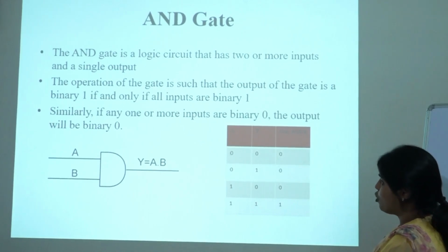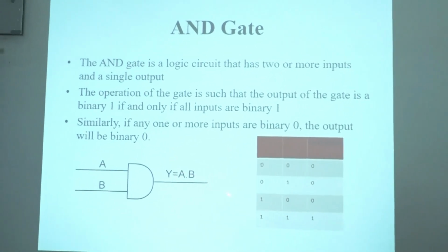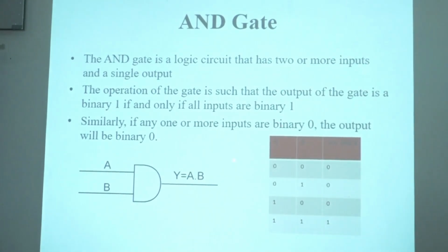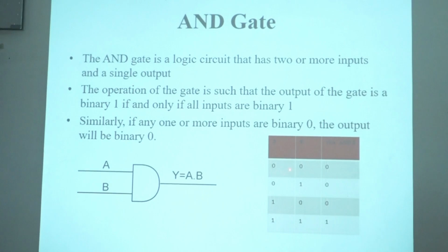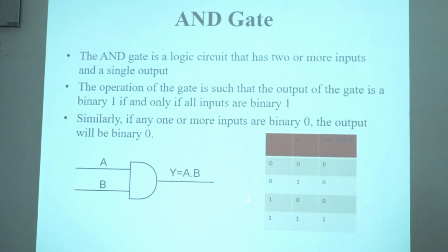This is called as AND operation or multiplication operation. Okay. Now when we look into the operation of the gate, what does AND operation do? When we discuss about this AND gate operation, we are taking two inputs here, A and B. So when I take binary representation of two inputs, I have four combinations, 0 0, 0 1, 1 0 and 1 1, right?